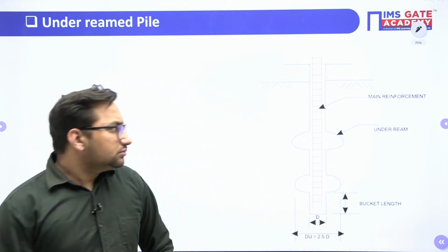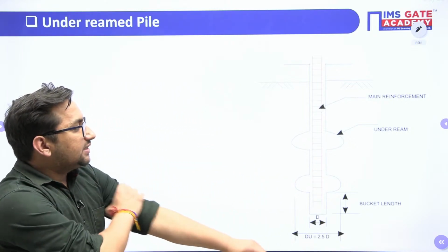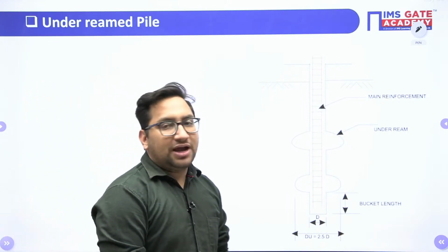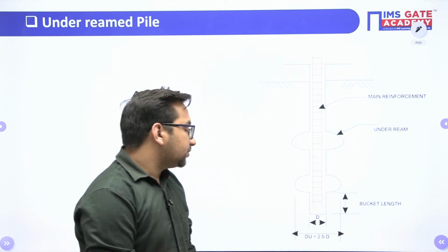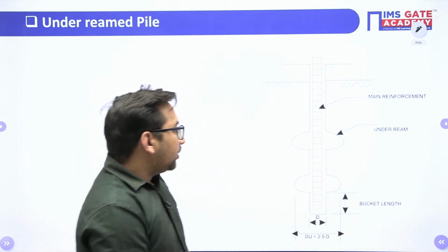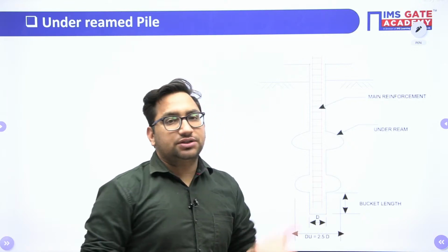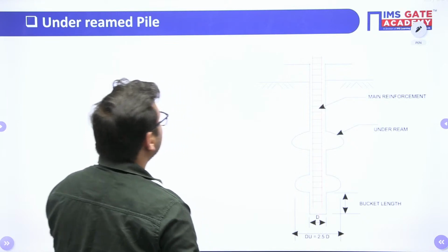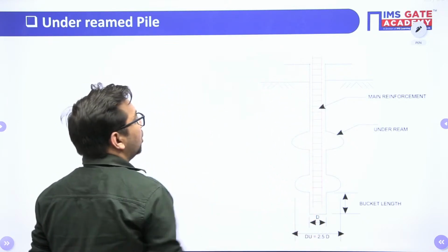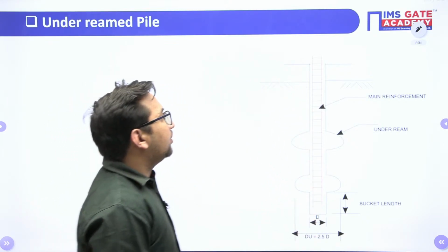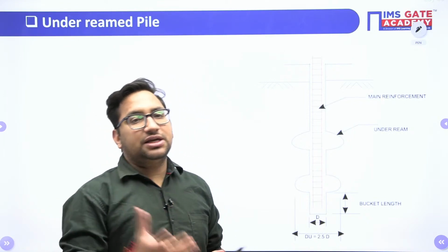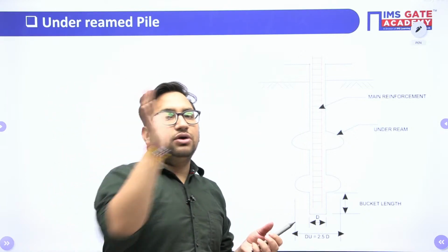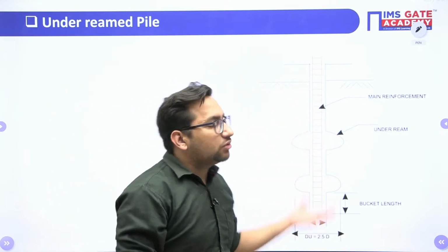Now, in expansive soils, like those containing montmorillonite, or black cotton soil, sometimes your foundation can be subjected to upthrust, that is, upward load. Let's suppose this is a pile foundation below a windmill. That windmill will definitely be in a location where the wind load is very high, so that wind load will try to pull out this foundation.